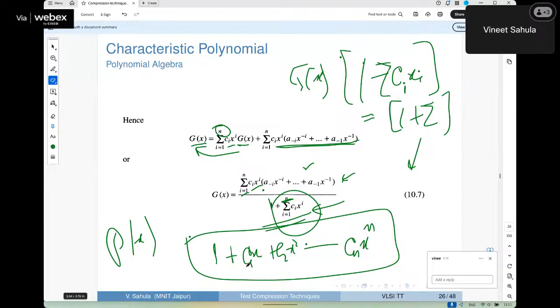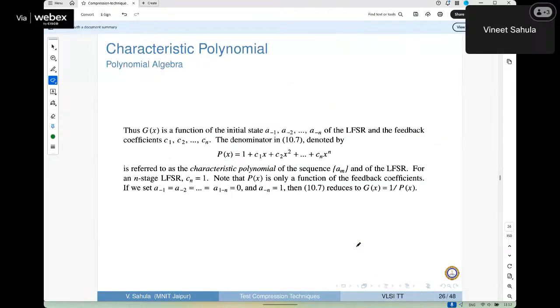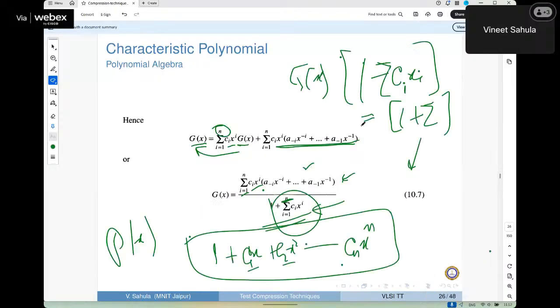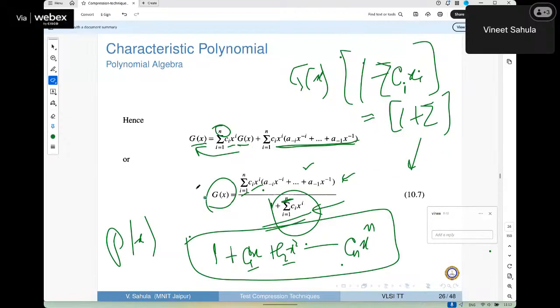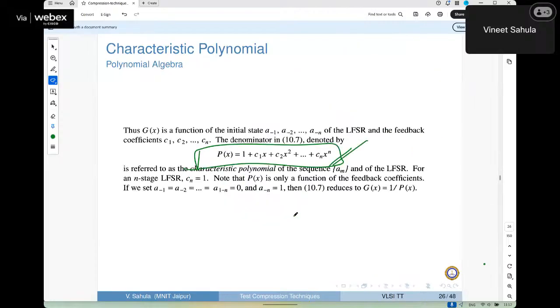But this LFSR is peculiar. We'll take it from that part. So this LFSR corresponds to this polynomial. That's all. We have proven that the polynomial corresponding to LFSR is this one. This is a generic polynomial output sequence. I'm sorry. This is output sequence of this LFSR. But this remains common to everybody. Hence, this is LFSR polynomial, characteristic polynomial. That's a derivation.